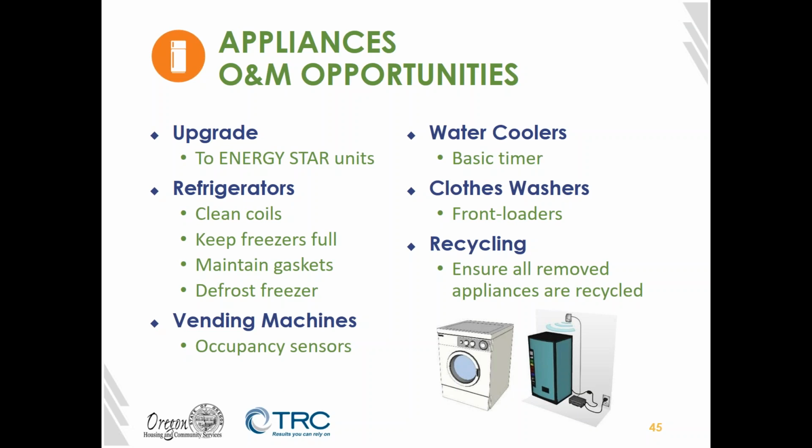For appliances, opportunities are we can upgrade to Energy Star appliances. For refrigerators, we want to keep the coils clean, keep freezers full, maintain the gaskets on our refrigerators and freezers, and then defrost the freezers if we get frost in them. If we have vending machines, we can install occupancy sensors on them. Water coolers like you have in offices, just a basic timer is really effective to turn it off at night. If you can have a 7-day timer, turn it off on Saturdays and Sundays when people aren't there.